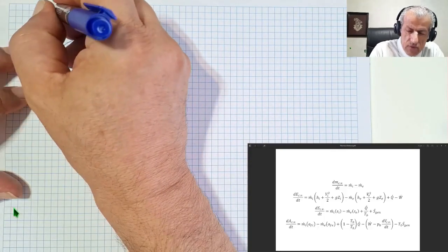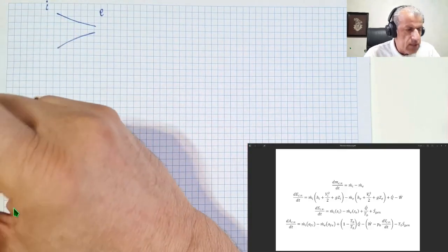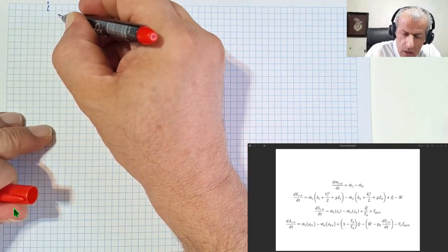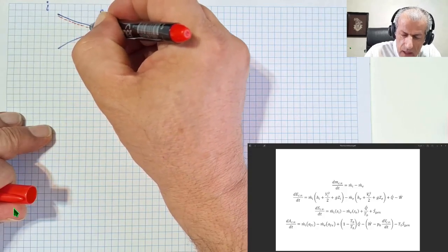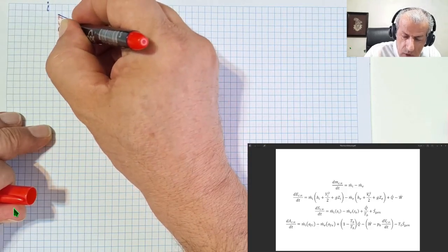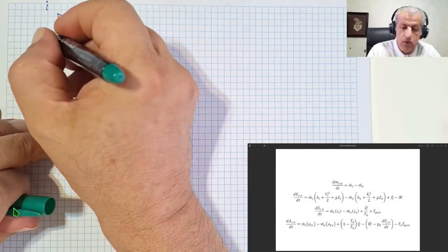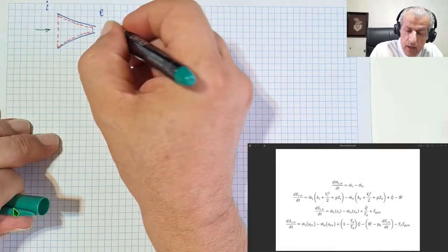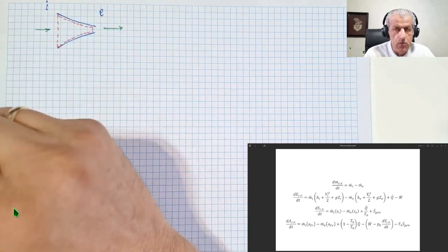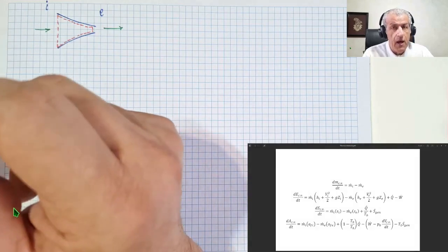So this would be a point I, which is the entry point, and this is point E, which is the exit point, and our control volume would be here. The nozzle has steady flow, so flow enters this nozzle steadily and leaves it, so there is no steam that remains inside this control volume. All that enters changes properties, but leaves from the other side.